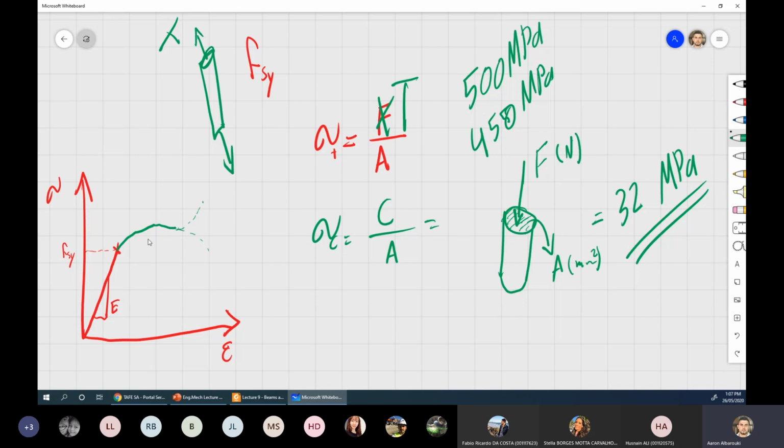But regardless, in both cases, all of this area here will reach FU, what we call the maximum ultimate. U stands for ultimate. FU is the ultimate stress this material can reach. So we have the yielding point, up to which the material keeps resisting and going back to normal, and then this point, the ultimate point. After this point, this piece of steel will simply fracture, be cut in half. That's the ultimate, where the material will completely fail. Obviously, all this part here is the plastic part.